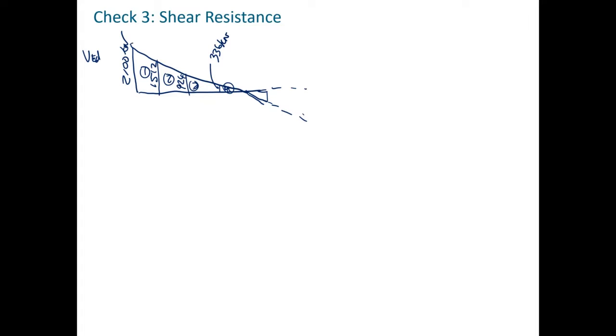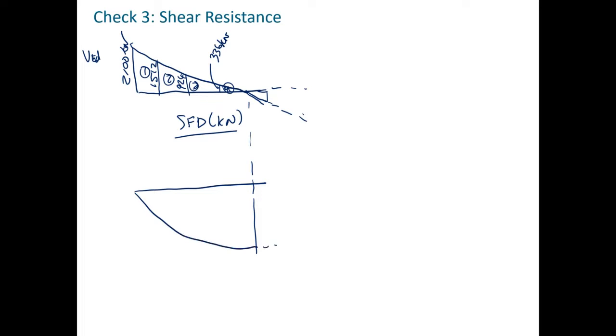Okay, so that's the shear force diagram, all in kilonewtons. And then the bending moment diagram, again, we've shown how to calculate this, and I've calculated the first version of this already. So we'd already worked out what the MEd at the bottom was at panel 4, which is 5250. I think getting all these other panels matching up.